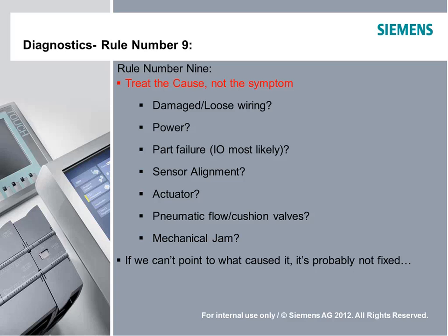Power. Power is an interesting one. Power failures and so forth can cause all kinds of problems with modern machinery. Modern DC power supplies also have a neat feature in that if you short them out, they turn off, and if you remove that short, they turn back on again. So oftentimes that can be the intermittent problem we're searching for. And we have ways of fixing that.